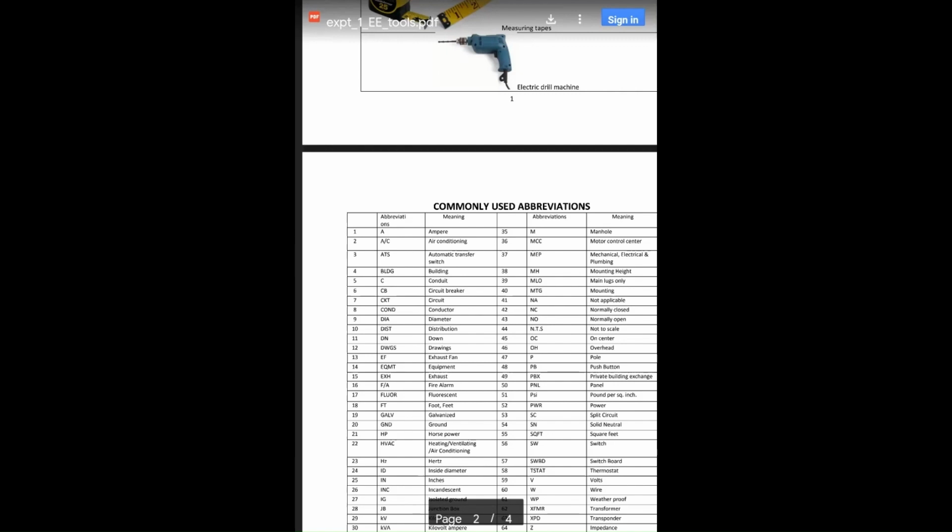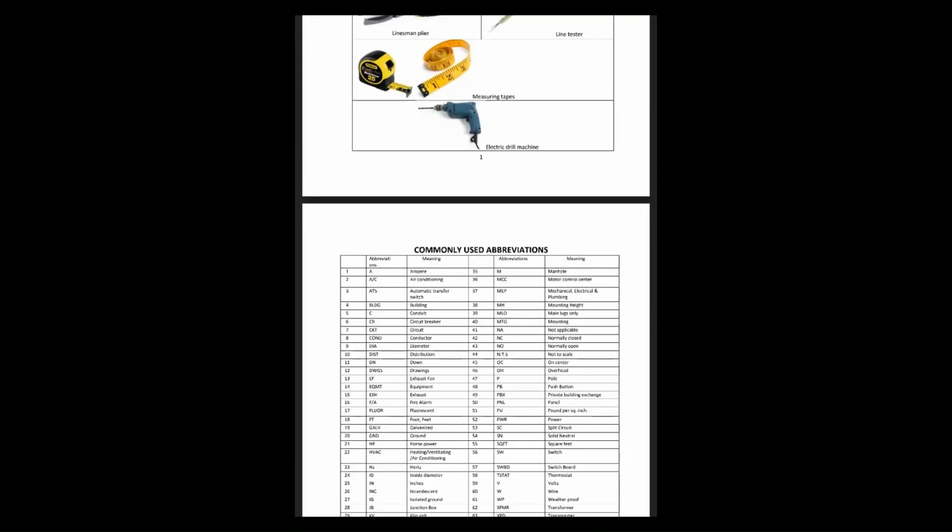Sometimes, if you are creating a study or a computer room and you want a fixed cabinet, the stone is drilled to serve our purpose. The drill has different bits, so as per our requirement we change the bit, because the thickness of every material is different.